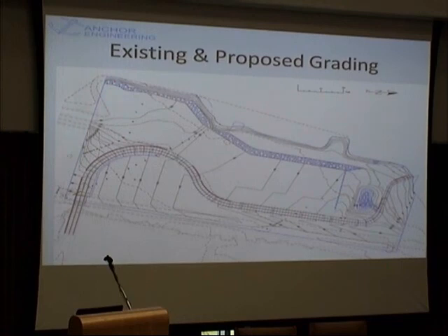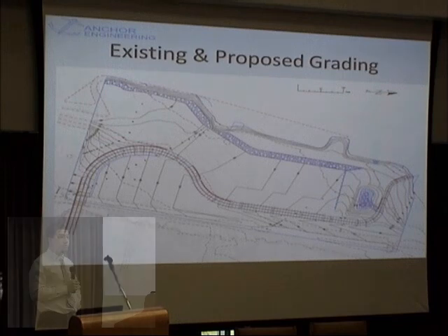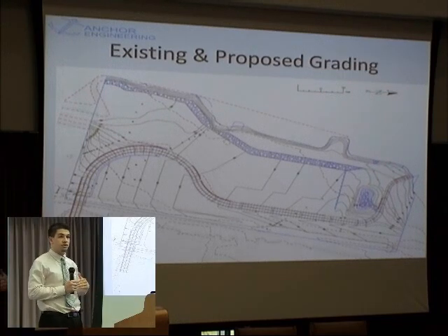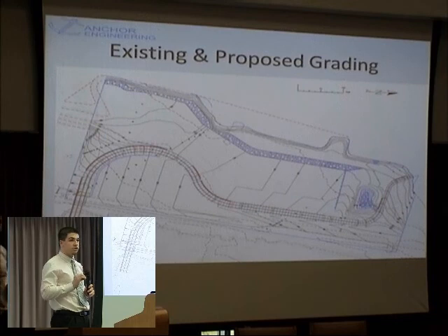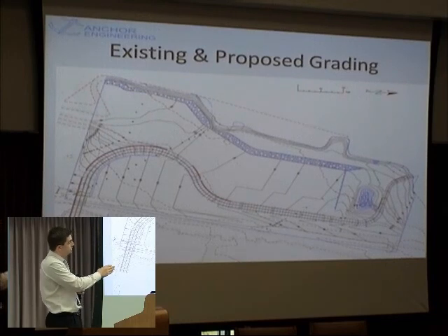This is the existing and proposed grading. On the north and south end, we tie into the existing grade. Our main objective was to take most advantage of the water scene. That's the primary objective on the Tiverton waterfront. So, along the south end, we have the first bridge. Next to it is the retaining wall. That's where we can have the different slopes and grades. From there, where the restaurant is, we have a flat slope. Right after the pier, it drops down so you can see right into the ocean itself. When you continue forth, on the retail we have a slight slope so the water continues down to the detention pond on the north end.